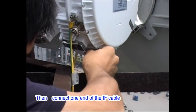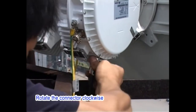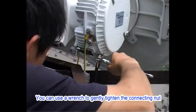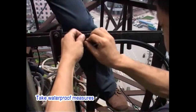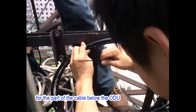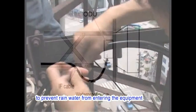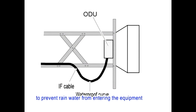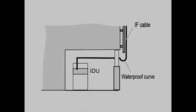Then connect one end of the IF cable to the IF connector of the ODU. Rotate the connector clockwise. You can use a wrench to gently tighten the connecting nut. Take waterproof measures for the part of the cable below the ODU and the part of the cable just outside the IDU room to prevent rainwater from entering the equipment along the cable and causing an equipment failure.